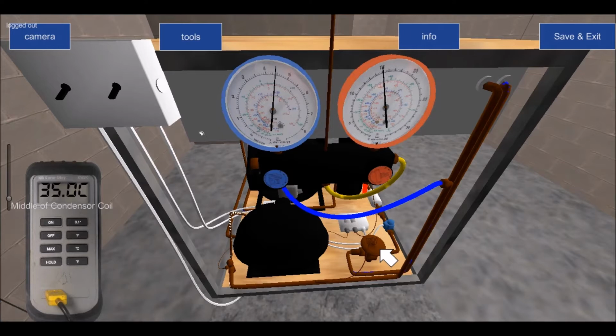So the most reliable way of determining what refrigerant is in your system, if it isn't labelled, is the pressure temperature relationship. You shouldn't come across a system in today's market that isn't labelled, because under F-gas regulations all systems must have a label on them. That label must say the type of refrigerant, the weight of refrigerant, the CO2 equivalency, in other words the global warming equivalency it has in terms of the CO2 benchmark, and the words 'contains hydrofluorocarbon gases as covered by the Kyoto Protocol'.